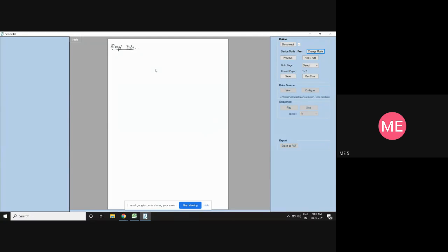So what I'll do, I'll draw a draft tube. Let us assume this is the exit of the turbine, and we'll give this as section 1. I will draw the draft tube, a conical edge, where the bottom portion should be dipped inside the water. So this is the water level. Then I will take somewhere here at the bottom as section 2, section 2 and 2. Okay.